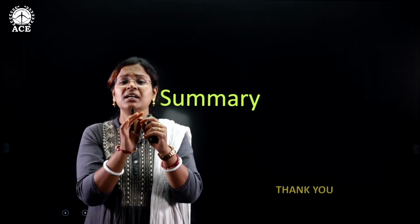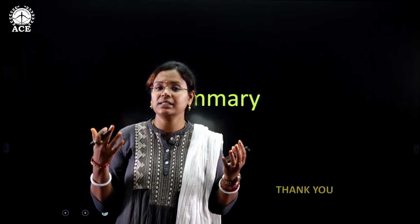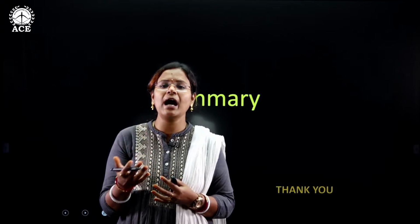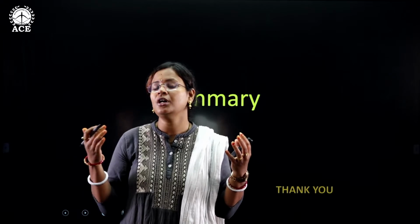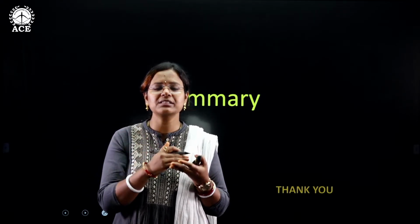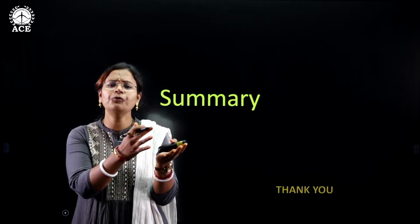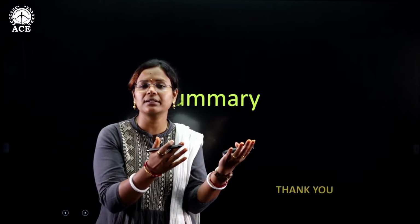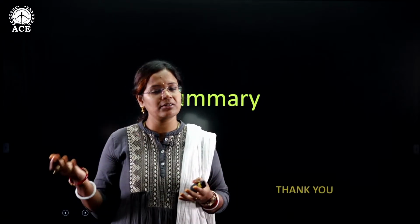Then later we have seen how a kinematic chain is formed where the first link is joined to the last link, and then different types of kinematic chains like 4-bar chain, single slider crank chain, double slider crank chain. Then we have also seen how a chain has a random motion and what to do in order to get a definite motion. What we have done is we have fixed one of the links and yielded a mechanism. And how a 4-bar chain is converted to a 4-bar mechanism, single slider crank chain to a single slider crank mechanism, double slider crank chain to a double slider crank mechanism.